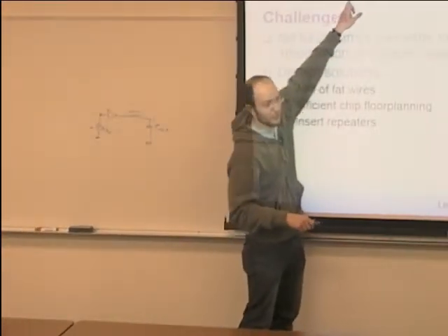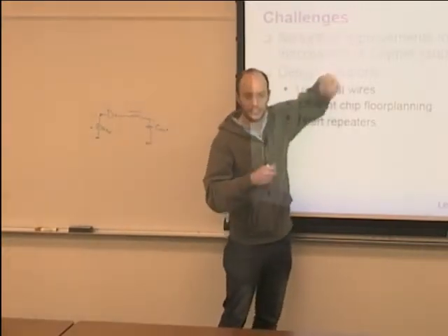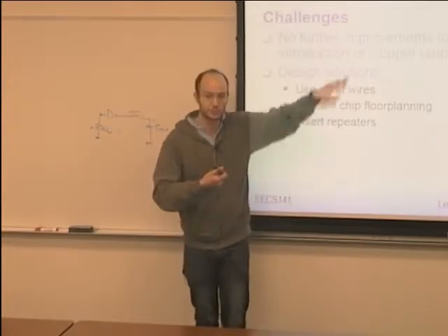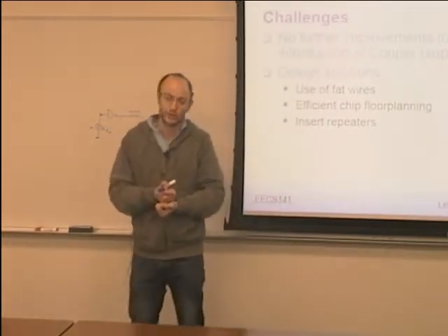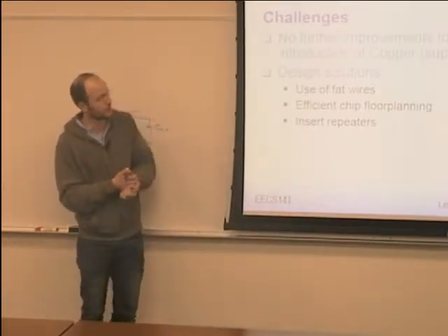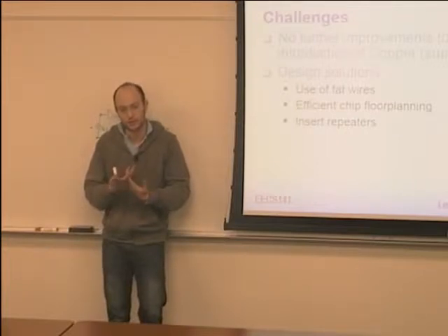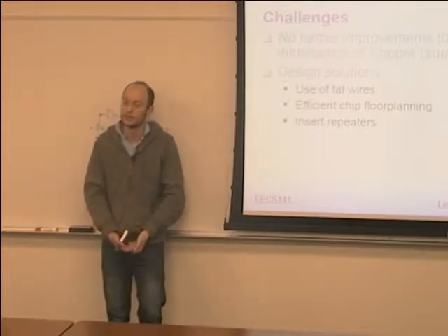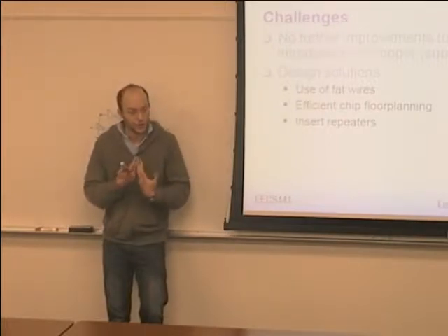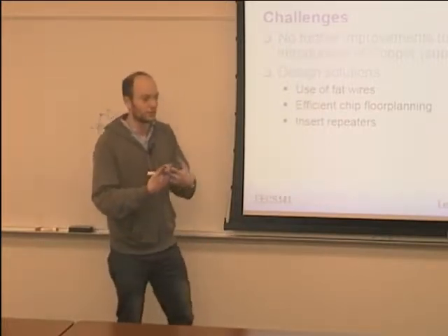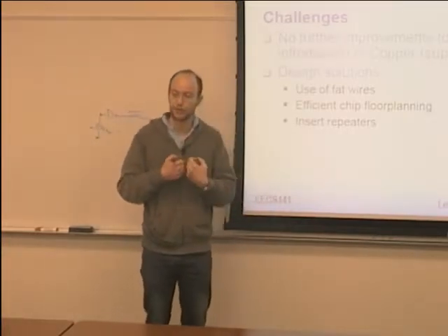This term, presumably the length of the interconnects, has increased. So this term has gotten bigger, and the logic delay has gotten smaller. In other words, the importance of the wires compared to the logic delay gets larger and larger over time. Does this make sense? And so now we are really in a regime where when you want to communicate from one side of the chip to the other, this must be very carefully planned.